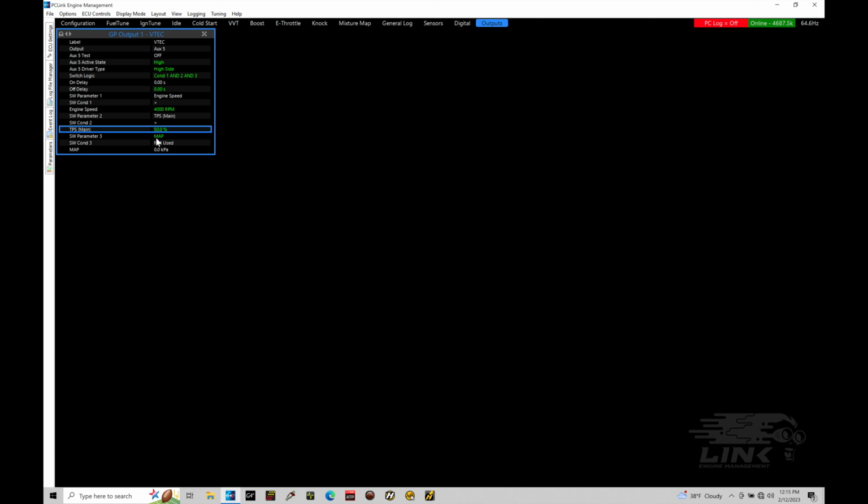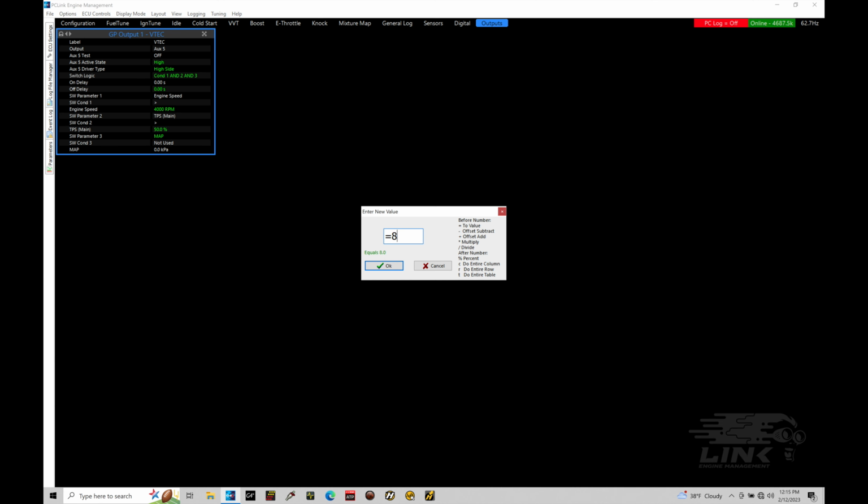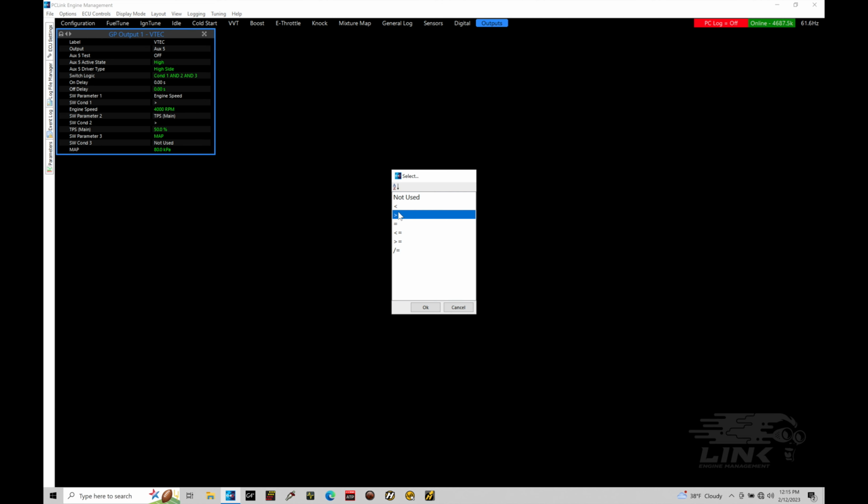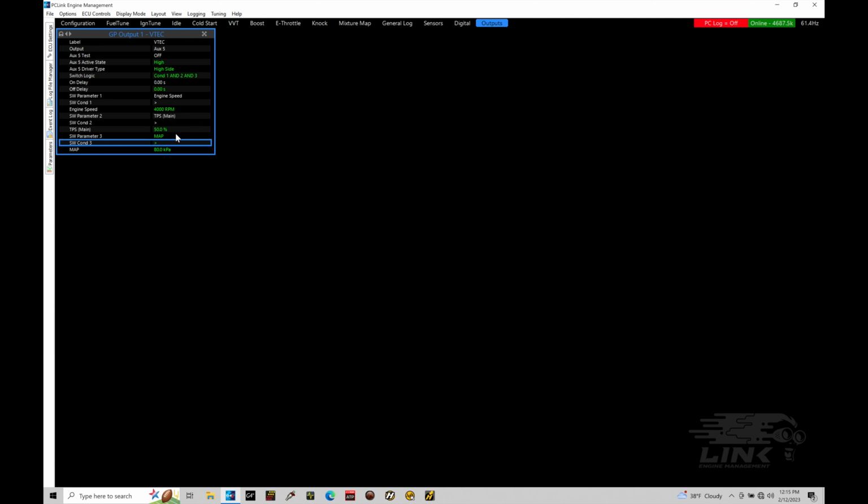The last parameter here under map, we're going to say when you're at least 80 kPa of manifold pressure for it to engage, and we're going to use our condition here as greater than. So we have to be greater than 80 kPa, greater than 50% throttle, and greater than 4,000 RPM, and the VTEC function will turn on. So we can see how to set up a general purpose output for a basic on-off control. Hopefully that makes sense here.